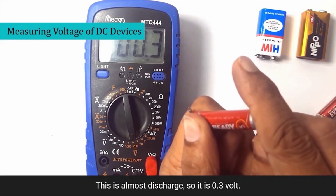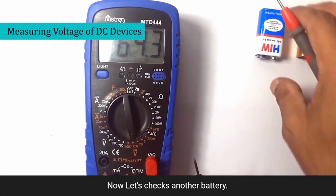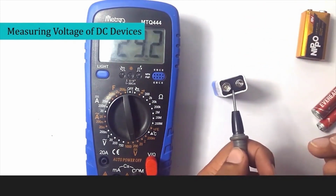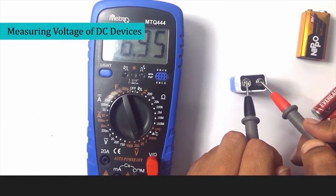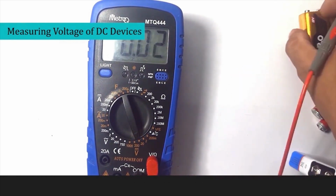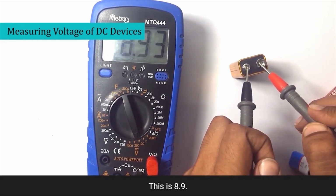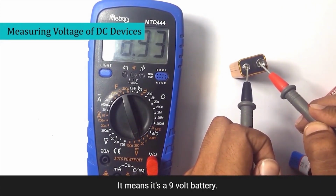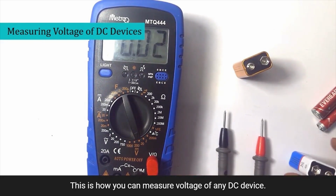This is almost discharged, so it is 0.3 volt. Now let's check another battery. This is 6.9 or 7 volt. Let's check another battery. This is 8.9. It means it's a 9 volt battery. This is how you can measure voltage of any DC device.